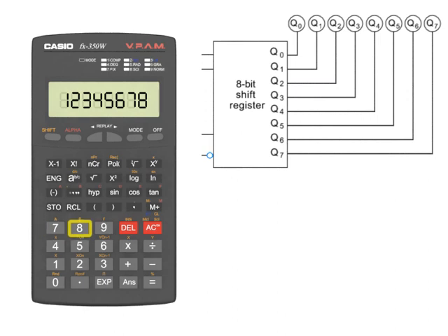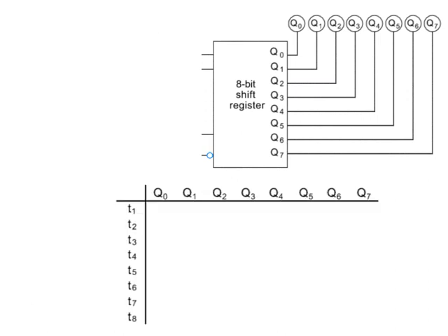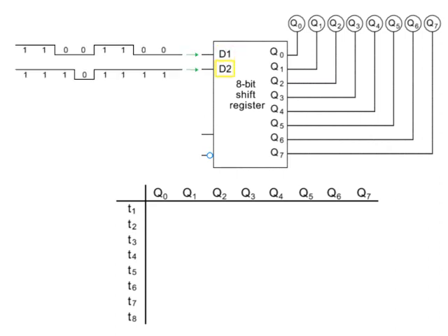Let's look at how a shift register operates by observing the shifting of an 8-bit register based on a series of binary data inputs. We have two serial inputs, D1 and D2, arriving at an AND logic gate. A master reset input at MR, which when activated by a low or zero input, will override all other inputs and reset the Q1 through Q7 outputs to 0.